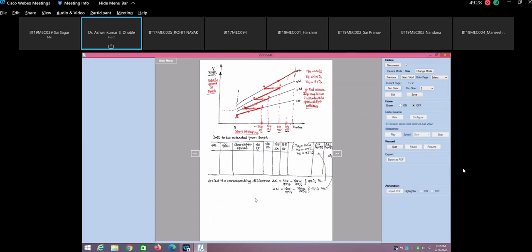Naturally, in 100% transmission efficiency, the engine RPM in first gear will be less compared to the engine RPM at the same speed for the 97% efficiency or 95% efficiency. So that additional delta n, which is going to be positive, that is the effect of the transmission efficiency. Are you getting it? So the transmission efficiency is directly affecting the engine RPMs for the same vehicle speed.